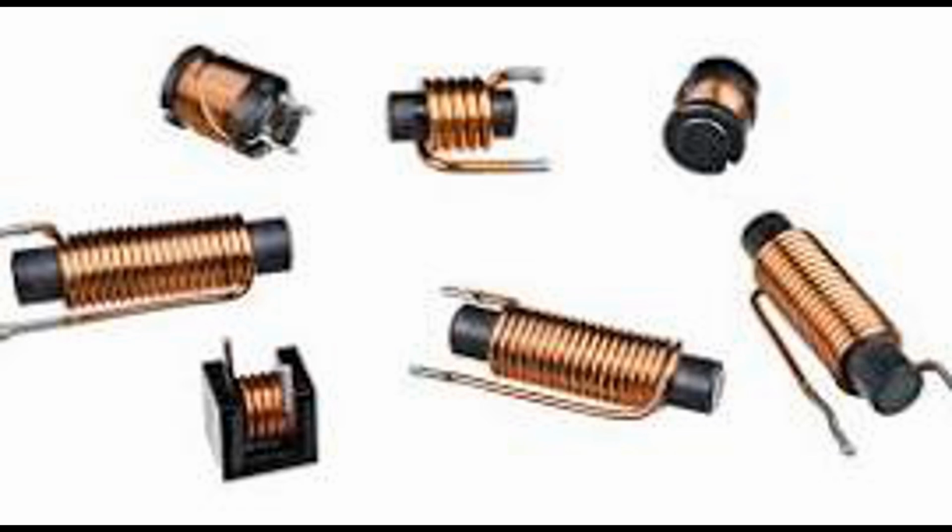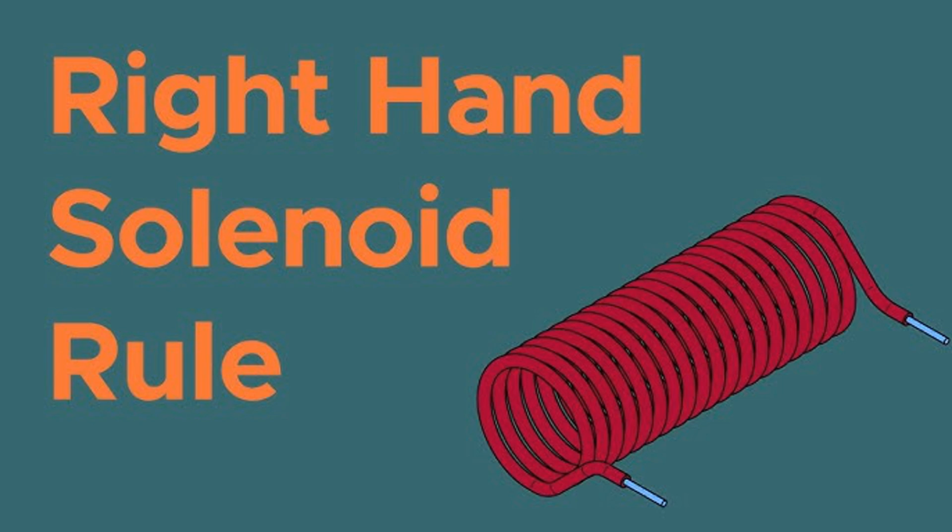4. Spring, optional. Material: usually made of steel or other flexible metals. Function: the spring is used to return the core, or plunger, to its original rest position when the electric current is turned off and the magnetic field disappears. Without the spring, the core might stay in the pulled-in position. Some solenoids use external forces like gravity instead of a spring.